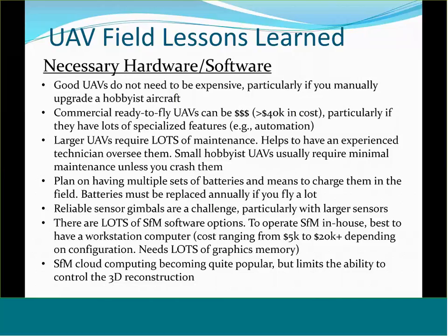Lots of times we focus solely on the platform, but we don't give a lot of attention to the gimbal that the sensors are mounted to. In my experience, the gimbals are the trickiest part of the platform. The sensors can be heavy, and that can cause problems with the gimbals. So if you're going to spend money on good equipment, you probably want to spend it on getting a reliable gimbal for your sensor.